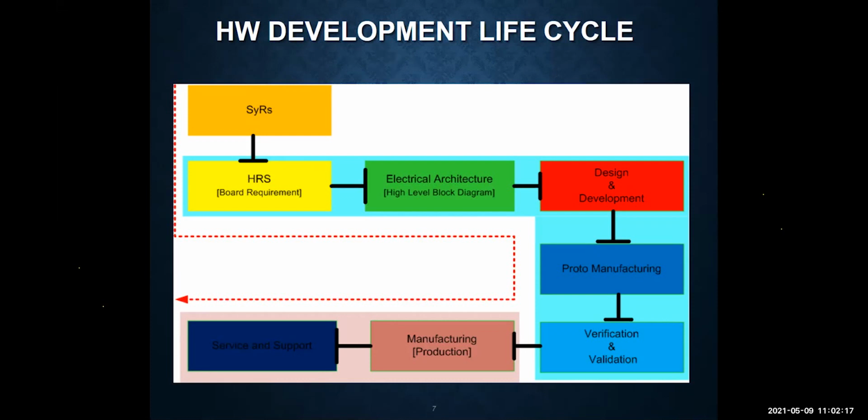As I said, the component engineer will also be assisting the hardware engineer. Sometimes the hardware engineer will also do the component selection, but not at the very low level. The component engineer will help select resistors and capacitors, which are very generic. The hardware engineer will set the requirements: help me select some resistors of 100 ohms, 10k, 100k ohms, and some 0.1 microfarad capacitors. He sets the requirement and the component engineer will select it. The hardware engineer will mostly be involved in selecting the processor and memory like DDR3, DDR4 or DDR5, and NAND flash or NOR flash.